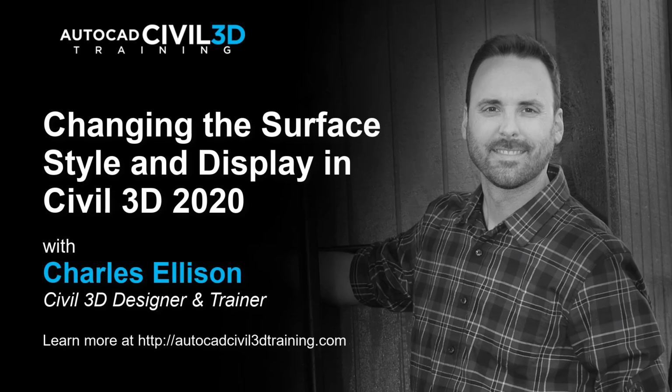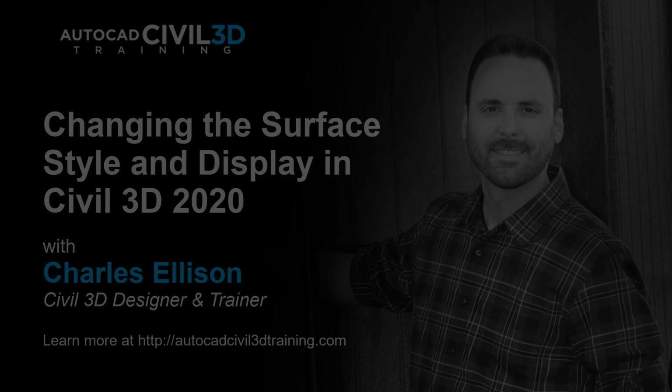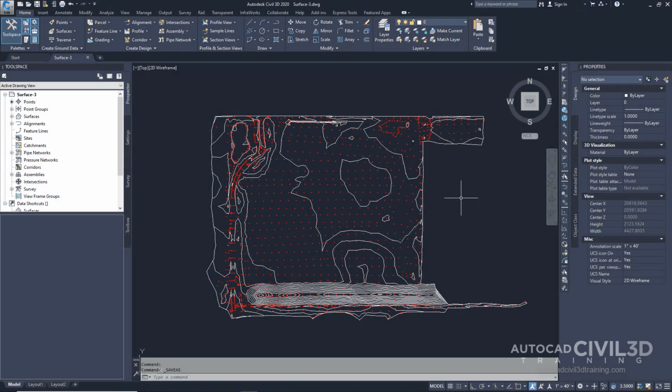Surface styles define how the surface components are displayed in the drawing. If you want to change the appearance of a component, either apply a different style or edit the style. The surface styles contain the following component parameters and component display settings for the creation of surface data objects, such as borders, contours, grid, points, triangles, watersheds, and analysis. So let's edit the surface style.